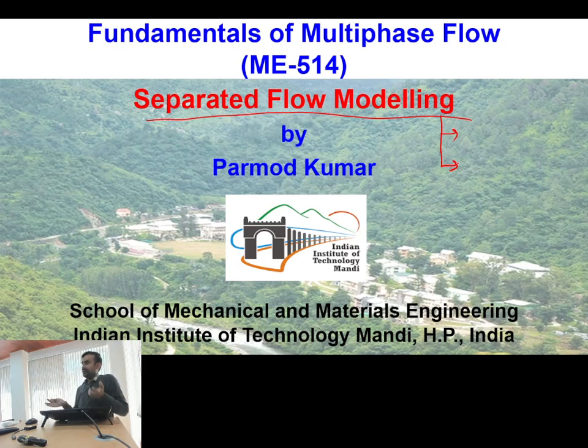Even if you have dispersed flow, or a well separated flow like annular flow or stratified flow, for annular and stratified flow this approach works very well. But even if we have dispersed flow, we treat that entire dispersed phase as a single fluid, and the remaining continuous phase as a second fluid. Okay, so that is the whole idea of separated flow modeling.